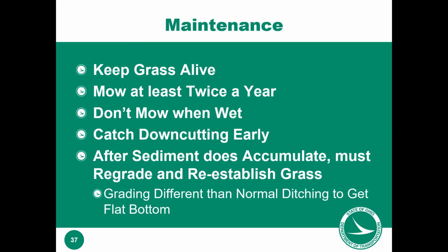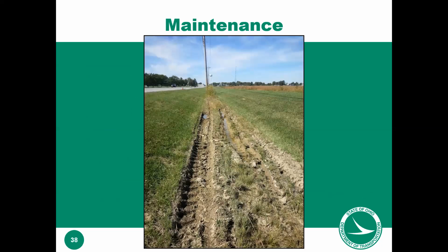So these ditches seem cheap and easy on the design side. And then when you get into actually maintaining them, they get a little more expensive because this kind of thing happens where you mow it when it's wet. The only real way to fix that to get a flat bottom grass ditch is to regrade, which is annoying because maintenance was being performed to mow it. And then you're doing more expensive maintenance to fix the maintenance you did. So these ditches are used a lot on transportation projects and do have some maintenance burden to them.